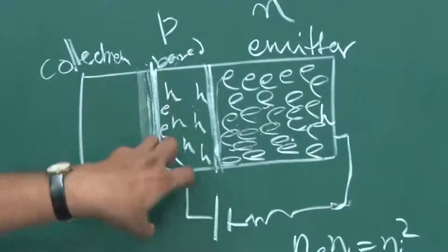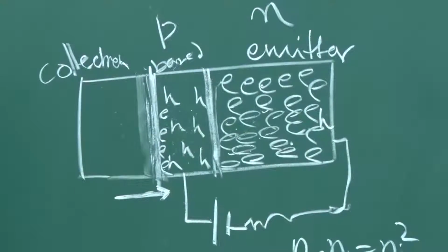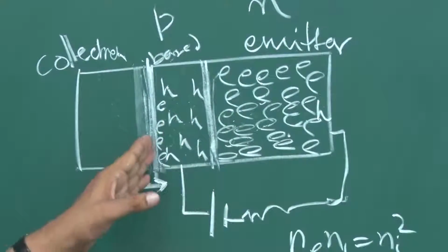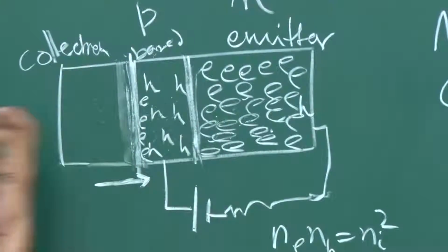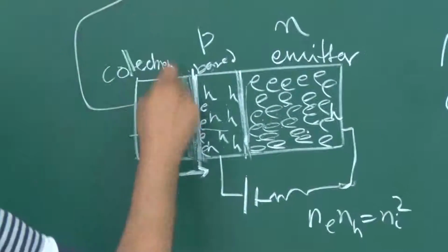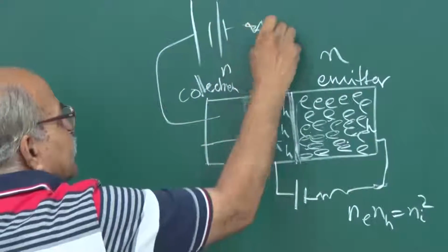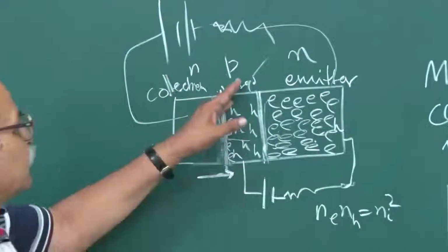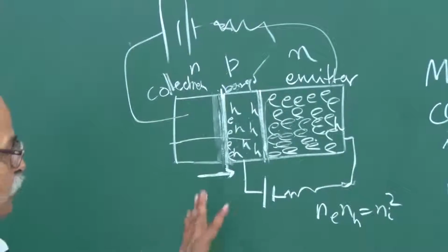And this electric field helps the minority carriers in making the reverse current, and therefore all these electrons which are crossing and reaching this depletion layer here where you have this field will be drawn towards this collector and will go to that biasing battery which is there. This is P, this is N, so you should have positive here, whatever resistances and all that. Okay, it's connected here, but anyway the potential difference is there, right?